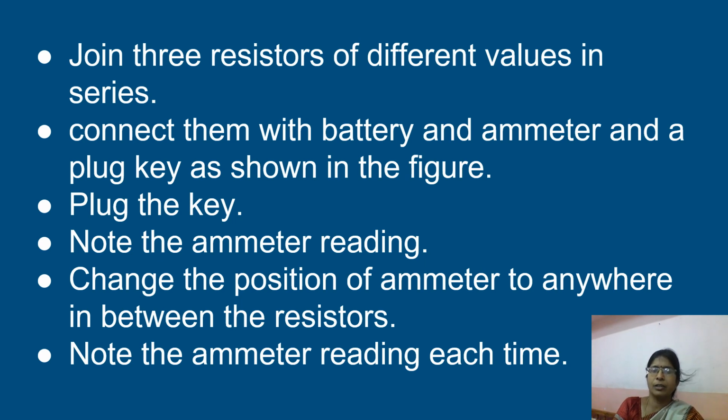After connecting the three resistors and battery and ammeter in series, then plug the key. Then note the ammeter reading. So you have connected all the components, that is three resistors, battery, ammeter and plug key are connected in series. After connecting, you plug the key. Then note the ammeter reading.